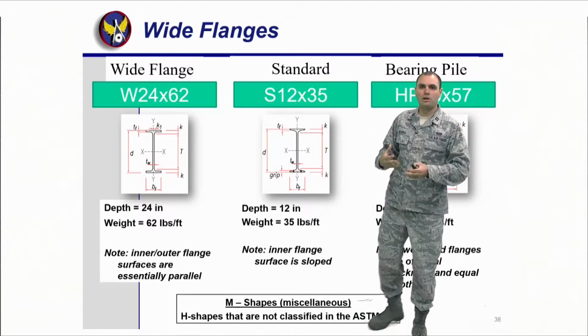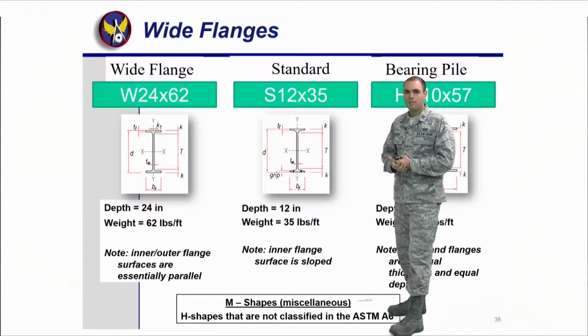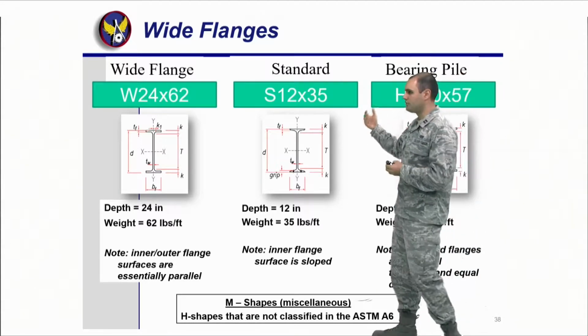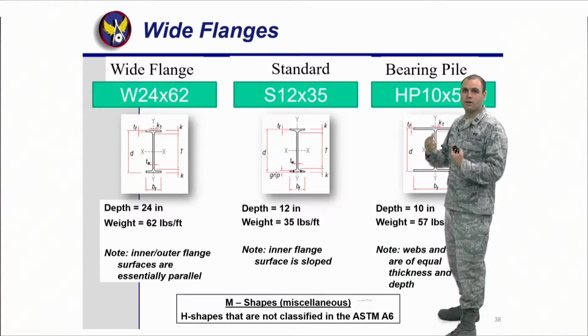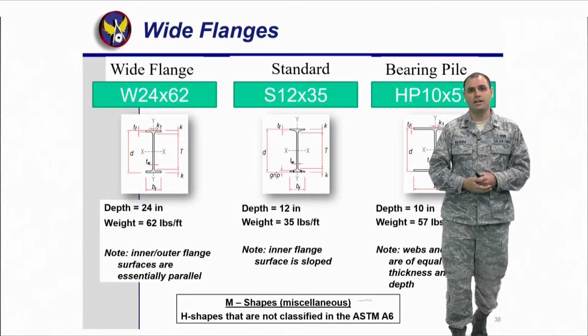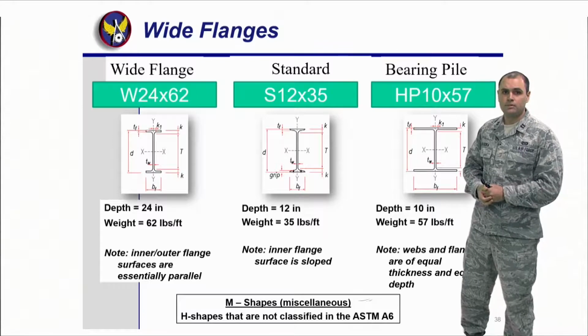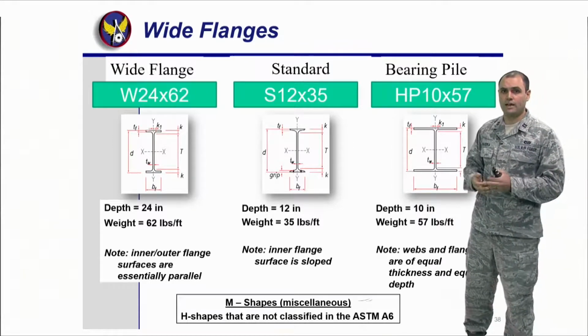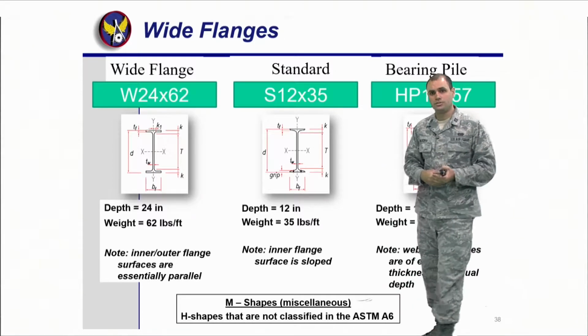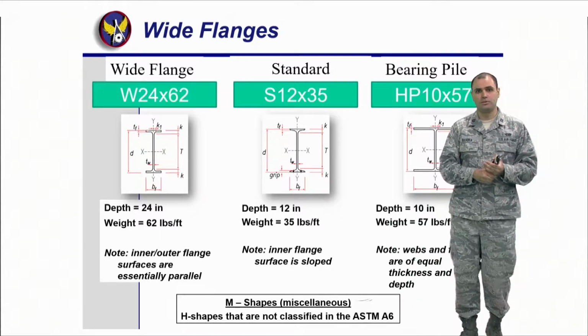And that's one of the nice things about steel. You're gonna see that in the shapes, they're gonna write down this nomenclature, W, S or whatever, and it's gonna tell you. So therefore, if you go look at a building and you say, hey, I'm gonna use an S12 by 35, yeah, you can verify. I got an S12 by 35. Let me just double check in the tables. Yep, depth is 12 inches. Weight is 35 pounds per linear foot.